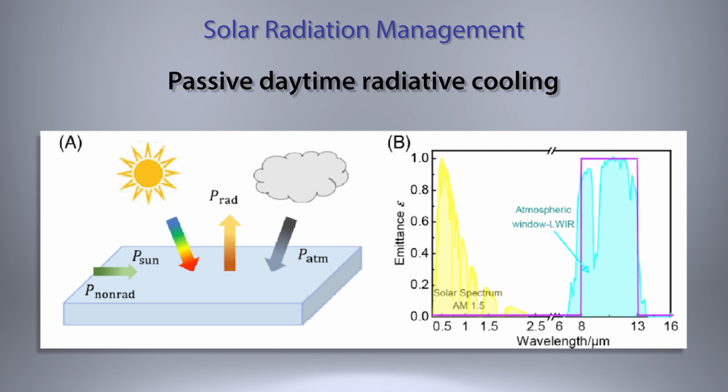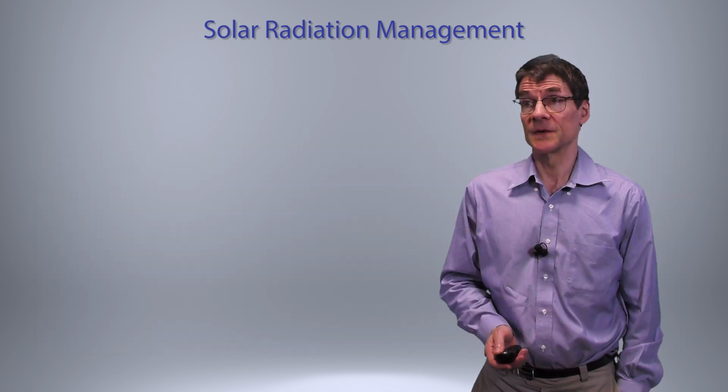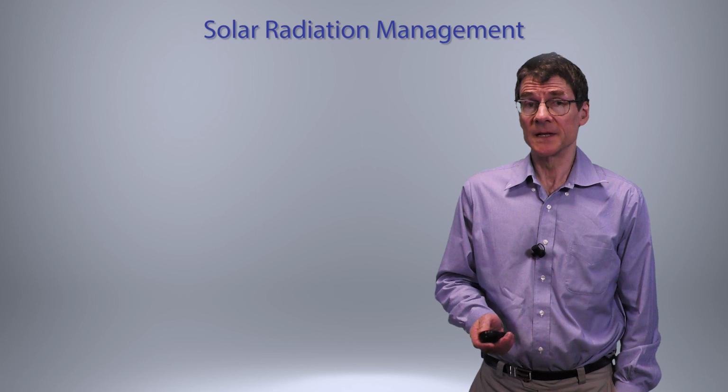And then there's a region in the middle of the diagram where there's no radiation either inbound or outbound. And then in the infrared, you have what's shown in blue. So you want less yellow and more blue. And the ideal is to have some kind of a surface which takes in none of the incoming radiation. And that's shown, if you can see, by the red line running along the horizontal axis. And then you have a step function, and you have a maximum band in the spectrum for re-radiation. So that's the ideal. As far as I know, no materials will accomplish that, but the closer they can get to that, the better.